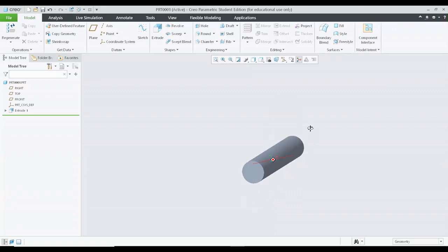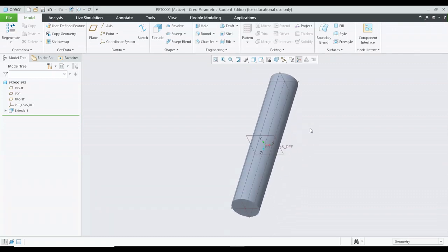This is a cylinder. And you can see the view. As I mentioned in the starting of the discussion of extrusion, if I want to create a cylinder standing on the ground, I have to select the top plane, right? But right now I haven't selected the top plane, I've selected the front plane. So this is something like a cylinder or a pipe which is placed on the ground. Clear? So this view is similar to what I'm trying to tell you.